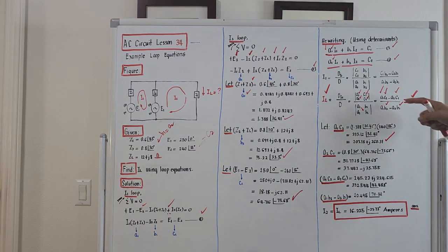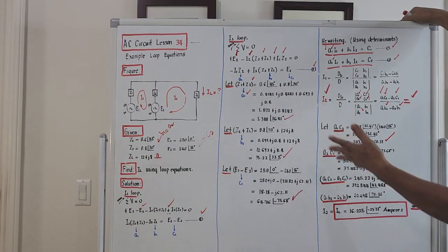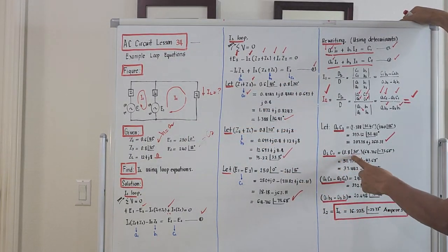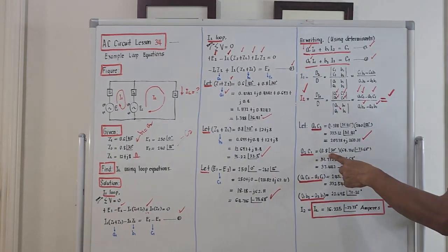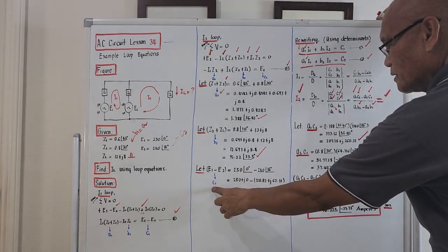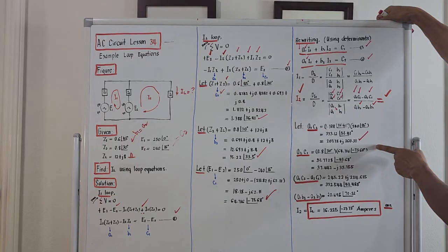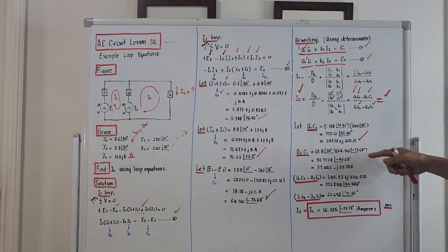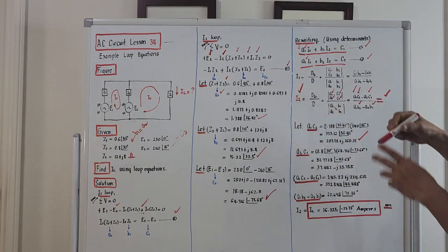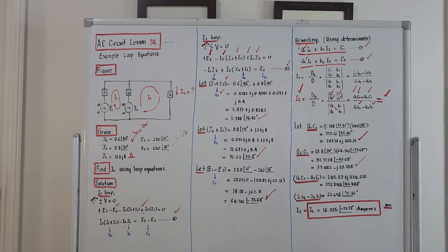How about the value A2C1? A2C1, where's A2? A2 is C sub 2, 0.8 angle 30. Okay, am I still on the camera? And the value of C1, do we know C1? Yes, we have computed C1 already and we express it in terms of polar. That is 64.716, angle negative 73.68 degrees. Performing this, converting to rectangular, because in here we will subtract. Okay, this is the rectangular equivalent.